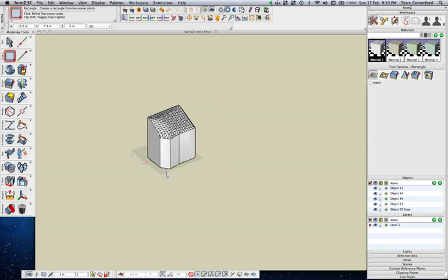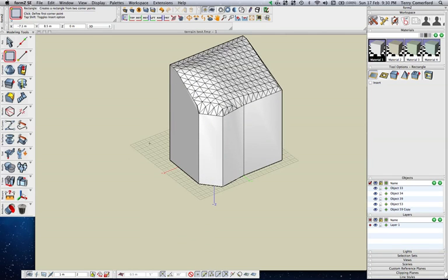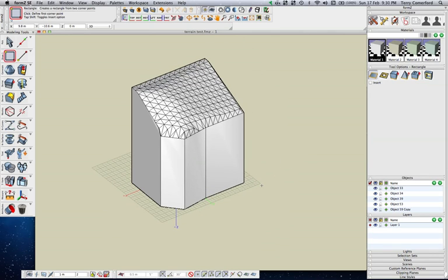If I hover back outside so that the standard reference plane is selected, and I press the F5 key, now when I hover over faces, the reference plane has been locked to where it was when you pressed the F5 key, and that's what I want to happen at the moment. Actually, I don't want that to happen just now, sorry. I'll just press the F5 key again to release that, so you can see how I'm hovering over.